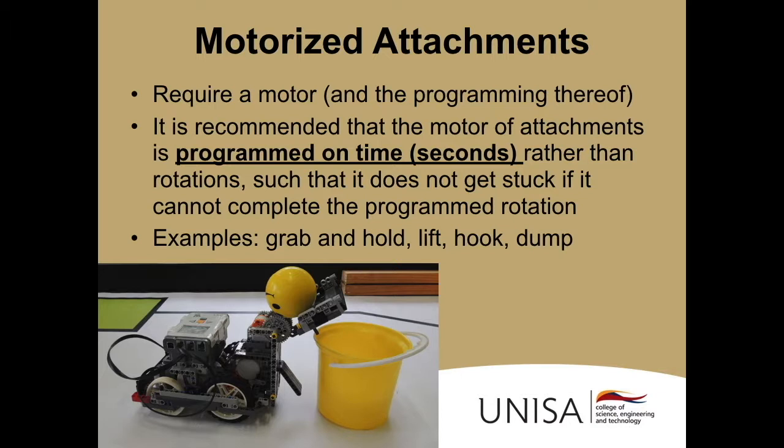And that's because if you use rotations and for some reason the motor cannot complete the rotations that you programmed because the attachment gets stuck on an obstacle, the program won't proceed to the next programming block, but it will be stuck at that step because the number of rotations are never completed. If, however, you program your motor using the time mode, then the time that the motor is supposed to move will elapse regardless of whether the motor is able to perform the rotations you anticipated or not.